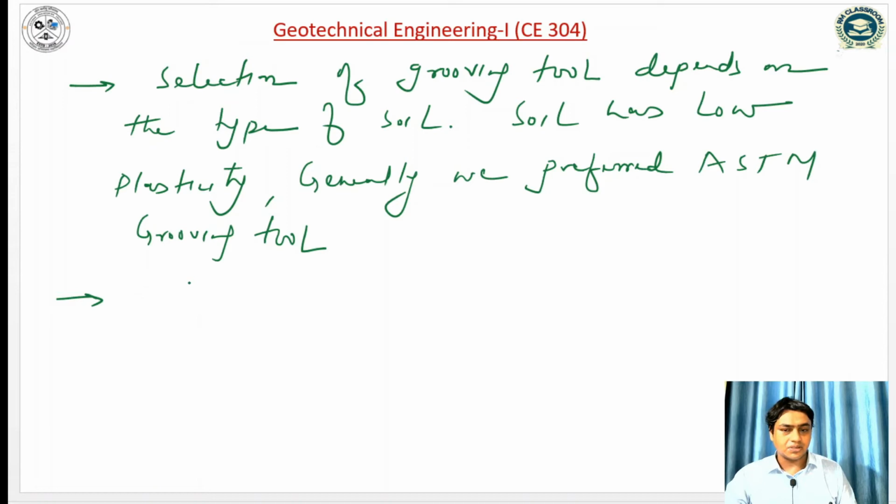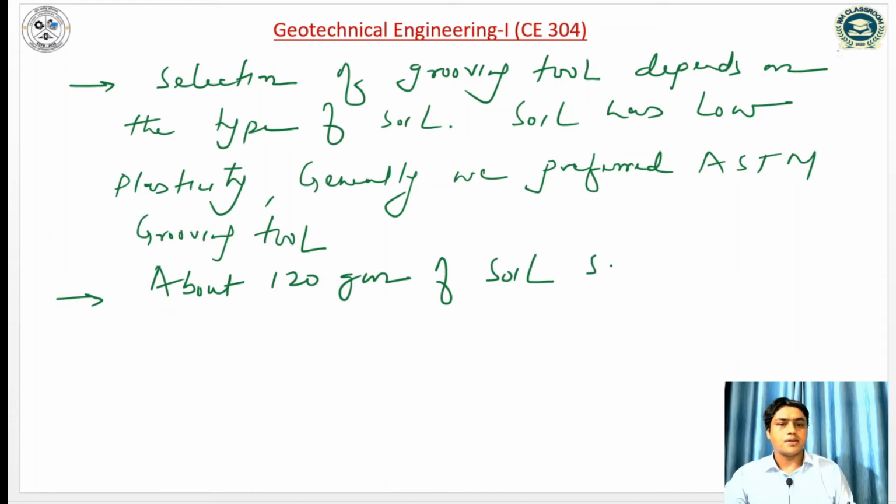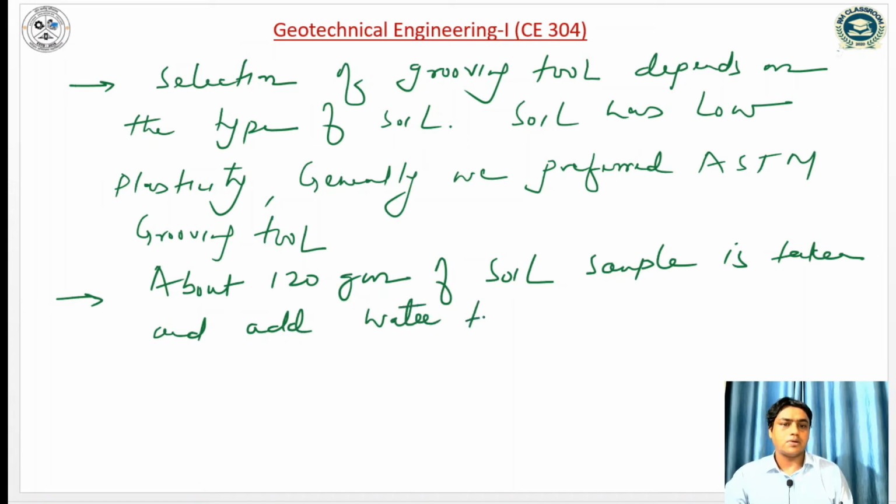You have to take at least 4 to 5 observations, and the number of blows should be in the range of 10 to 40. So if I write the procedure: about 120 gram of soil sample is taken and water is added to make a soil paste.